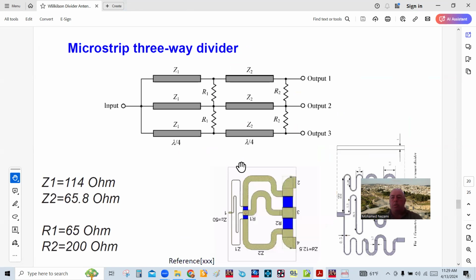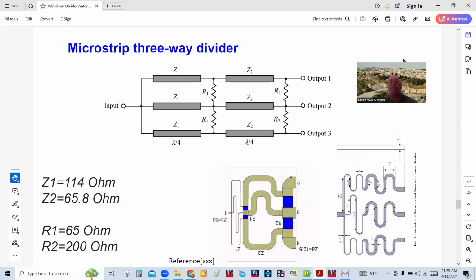All right, so next, let's do one more, which is the three-way power splitter. I know a lot of people don't get into this situation, but a three-way power divider in feed array networks for antenna array is very useful and very common, because in a lot of cases you end up with an array, let's say a subarray of length 1/6, for instance. That's where you need a three-way splitter, okay? In a lot of cases, a three-way splitter is more efficient than deriving things. It's for the odd number of splits, okay?